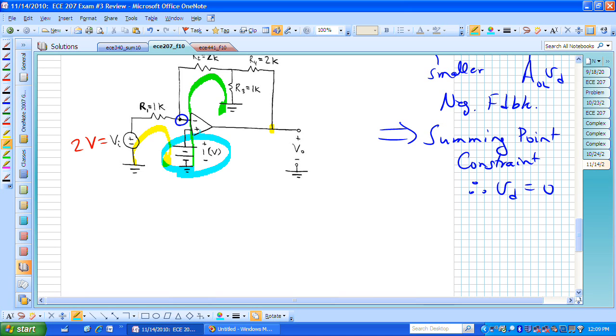It's raised to 1 volt with a DC source, so we'll have to account for that when we're doing these KVL loops. We'll then probably do a KCL there, and a KVL around the output loop. Again, we're starting at ground and finishing at ground, so that is actually a loop, and you could connect it that way if you wanted to.